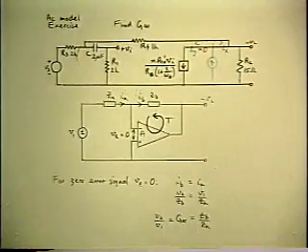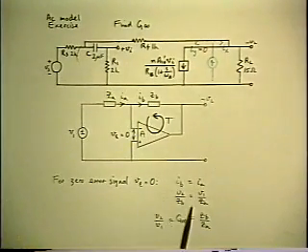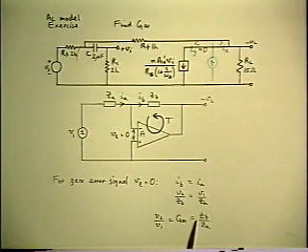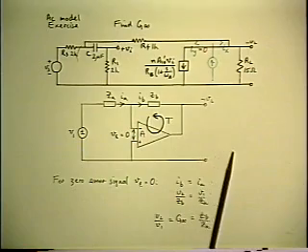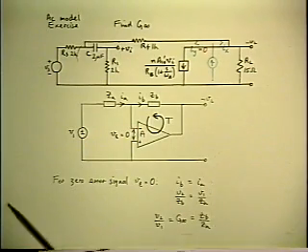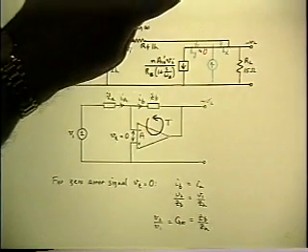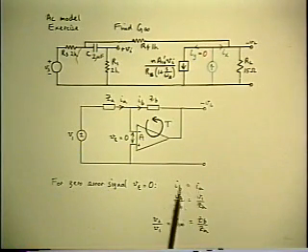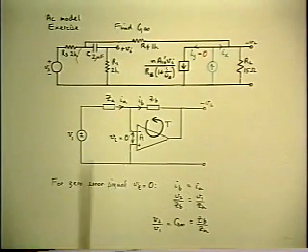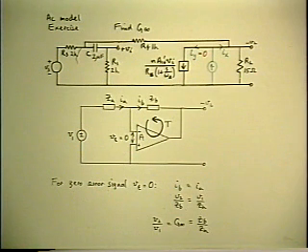I talked about this already when I emphasized that the normal way that most people calculate the gain of this feedback system is to assume infinite loop gain, which is what allows you to say that the two inputs to the forward path are equal for zero error signal, and that's the condition you need to arrive at the result.